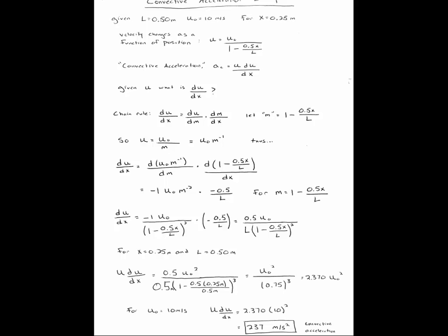And so in that nozzle, whatever goes in the nozzle has to also go out. So if you put 1 liter in, then 1 liter will have to come out. Like inside an enclosed space, there's no capacity for storage or accumulation. And so you're asking about the area and the diameter. It's the decreasing diameter that decreases the area, and then that in turn is what increases the velocity. I'll show you this way of calculating it, and then if you can find an easier way, I'd be delighted to see it.